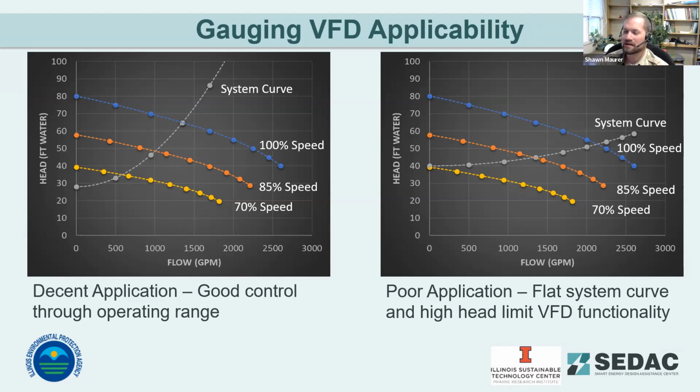But going back to the VFD systems before we jump into the poll, just looking at the applications here, one thing to pay attention to, if you have access to it in your design documents, is the approximate system curve the pump was designed for, with the pump curve laid over top. It lets you know what your design point is. At that design point, the system and pump curves should have a near perpendicular crossing for effective control.